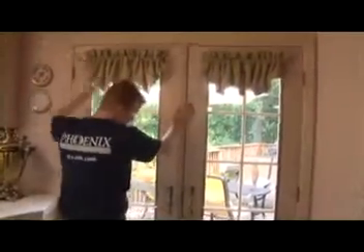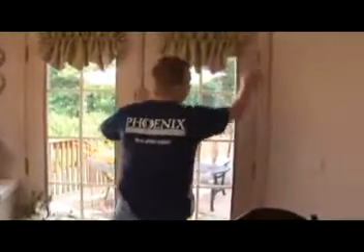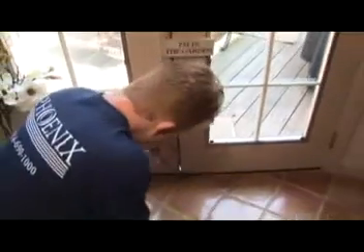Okay, so we're going to check our exterior doors to see if there's any air leakage. And because the blower door is running, it's pulling air out of the house, which is going to pull air in wherever there's air infiltration. And if we go down to the bottom of the door here, we feel a pretty big rush of air. And as you can see, there's a clear gap to the outside. So this is a weakness in the thermal boundary here, and something that should get fixed.